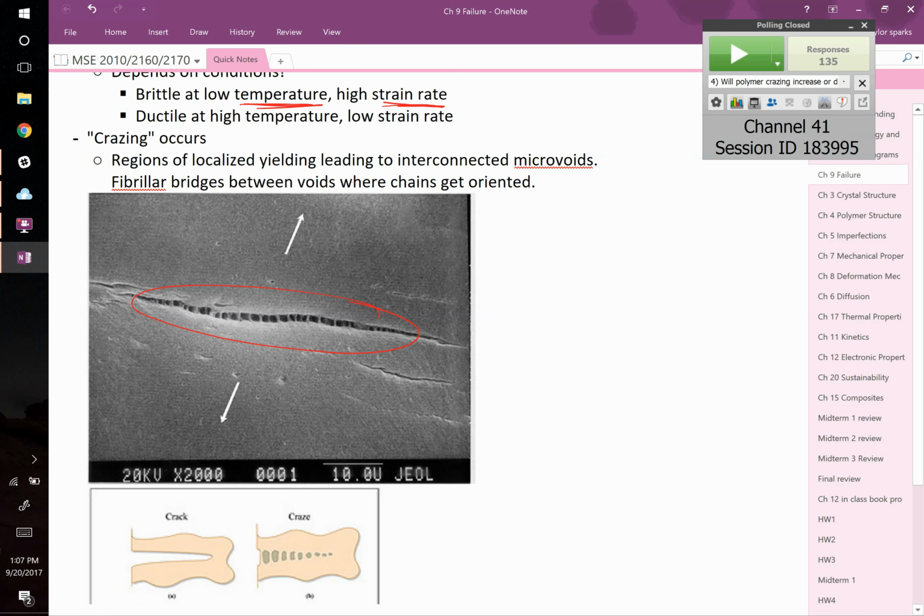Yeah. Remember, the two rules of thumb is if you make it harder for the crack to propagate, like a secondary phase like you added, maybe it hits that secondary phase and has to go around it or something. Or, yeah, question, Rosa? So are you saying that that's a crack, but it's characterized by crazing, and crazing makes the crack harder to crack more? Yeah, because for that crack to continue delaminating, it has to pull out those bridges, basically.